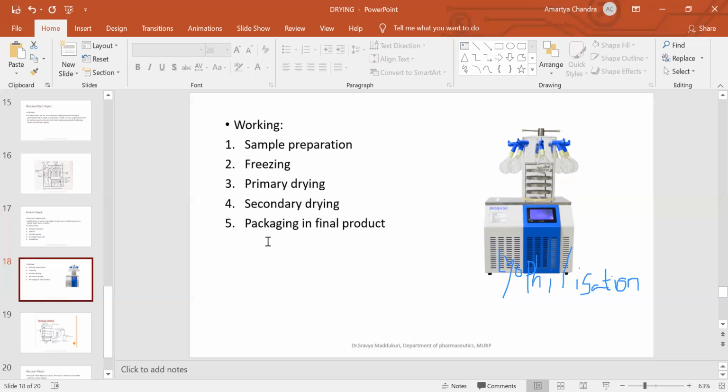Now, traditional freeze drying is a complex process which requires careful balancing of the product, with many techniques involved. In this process, water is removed from a product after it is frozen and placed under a vacuum, allowing the ice to change directly from solid to vapor state. Right?